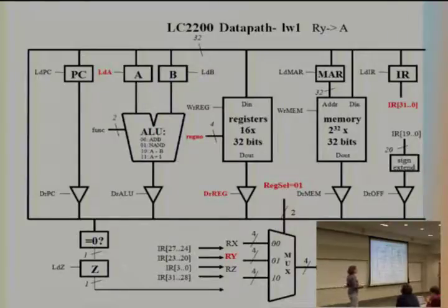So now if you would make a table of these, basically all these red signals would become 1, all others will be 0, and you basically get the current state. And what would be our next state? It would be load word 2. This is state load word 1, and each one of them would have a particular code. If you remember in our control unit, the register state had the 5 bits, putting them back into the ROM. So those 5 bits would determine all our possible